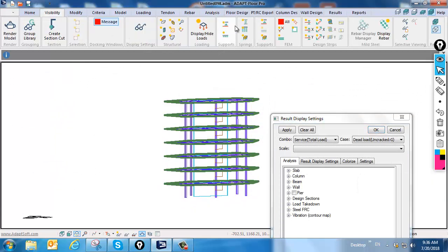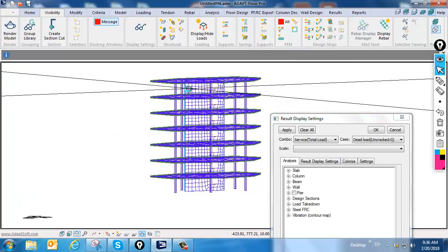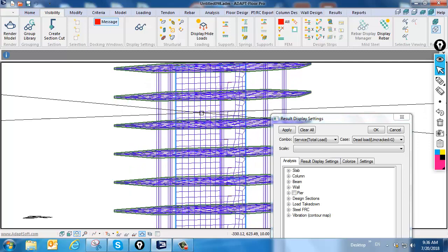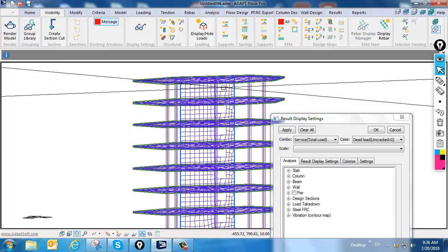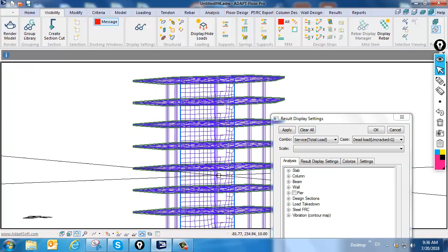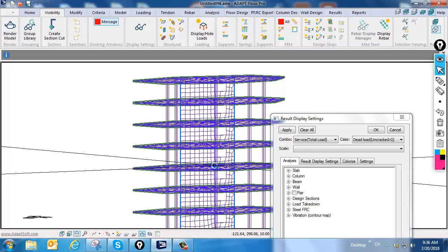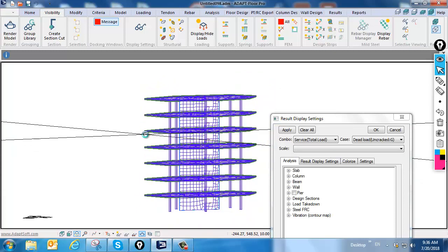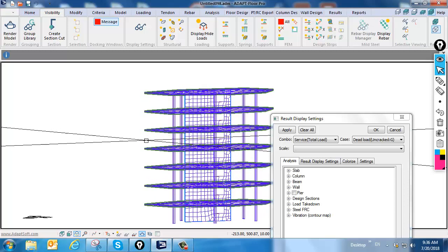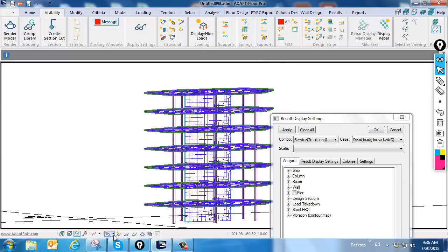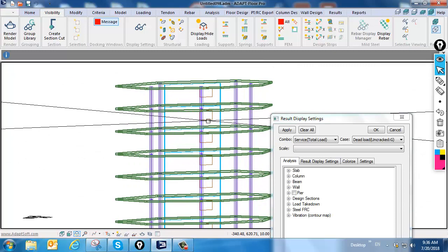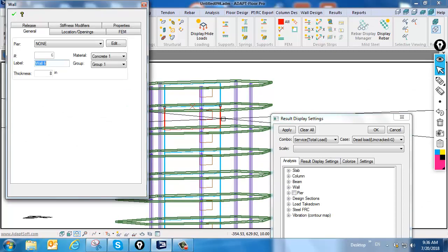I'll go back to visibility to view the wall meshing. And now you can see the wall meshing is much tighter because now it's using, again, a similar approach to slabs. We're using a sparse meshing algorithm, and we have the consideration of wall openings taken into account. If you have a situation where you might want to disregard one particular opening but consider other openings while still taking advantage of the new options, what the user can do, let me go ahead and set the default display. Let's say that we don't want this opening here to be considered.